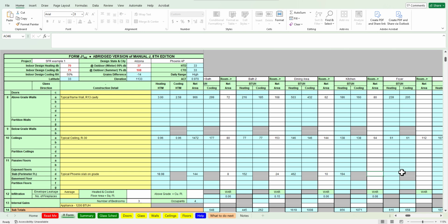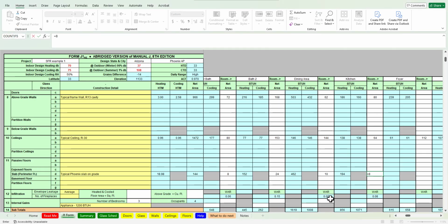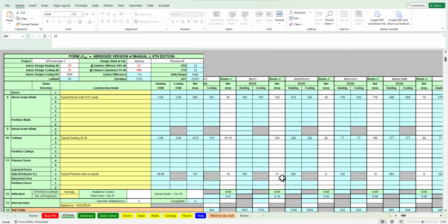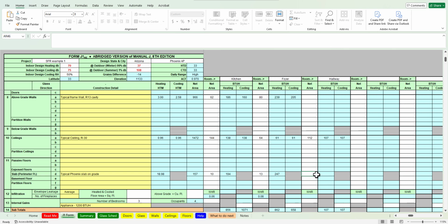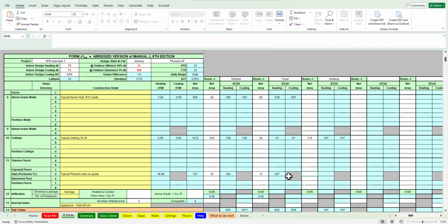Okay, now the foyer has 2 exterior walls right here, so this exterior and this exterior. So we said this was 8 by 5, so equals 8 plus 5. Notice I'm not doing multiplication, I'm doing addition. It should be all just addition, because we're not looking for area. And the hallway obviously has no exterior portion to it, so we do not include that in the floor.